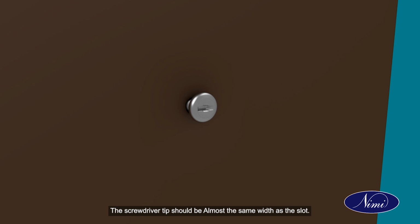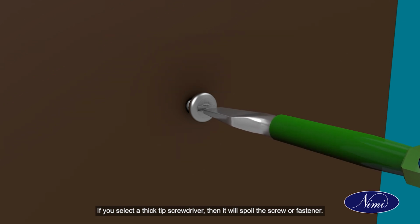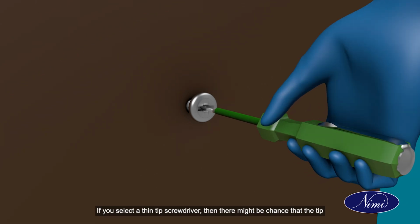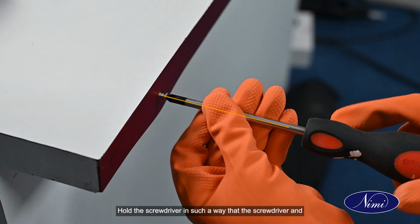The screwdriver tip should be almost the same width as the slot. If you select a thick tip screwdriver, then it will spoil the screw or fastener. If you select a thin tip screwdriver, then there might be a chance that the tip may twist and damage the screwdriver. Hold the screwdriver in such a way that the screwdriver and the fastener are in the same axis.